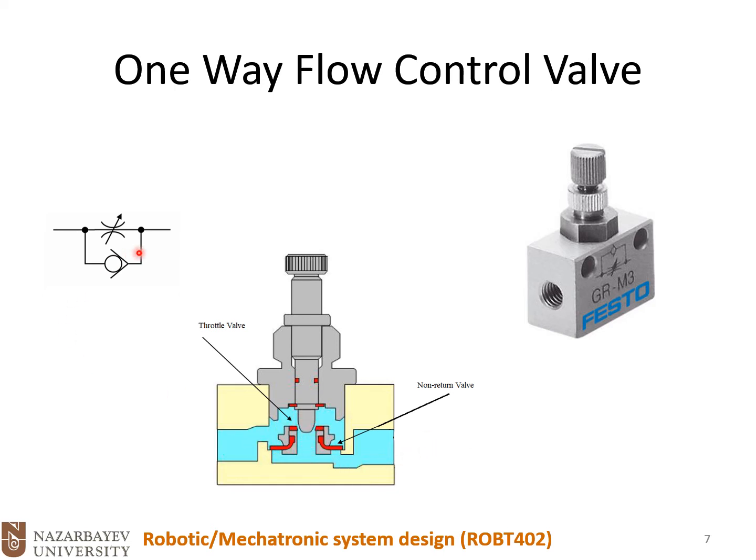Similar to the symbol, if the air flows from left to right, it has to go through the throttle valve. Once the air wants to flow from right to left, then it could push back these plugs, or these obstacles, and the air could flow freely without any restrictions, and it doesn't need to go through the throttle valve.